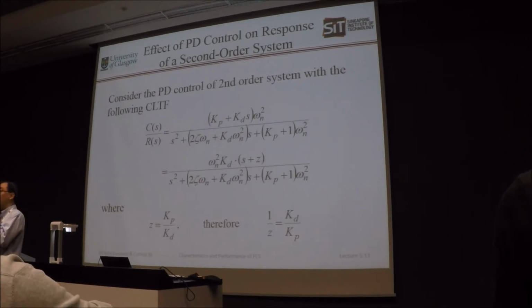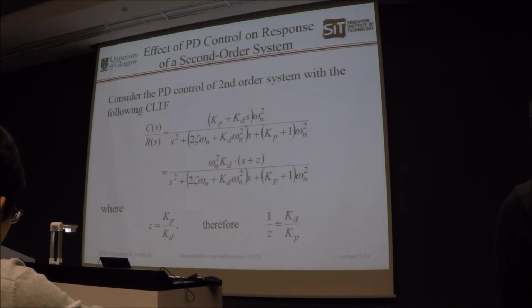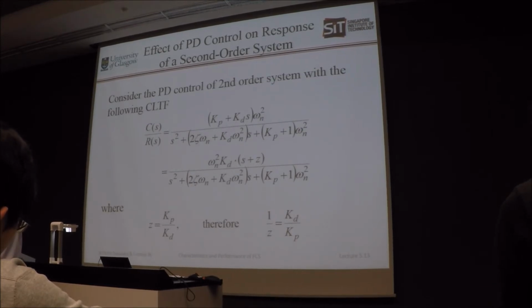So closed loop feedback primarily changes your closed loop pole location. But what about the 0? The 0 is something that unfortunately you cannot change. You can practice 10 times, 1,000 times, and you will see that if I place a 0 in the forward loop, when I close the loop, that 0 stays put at that location.